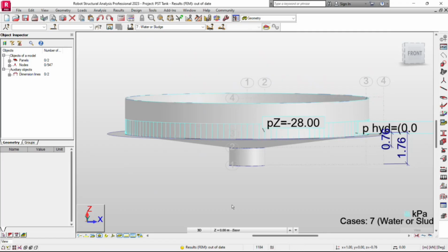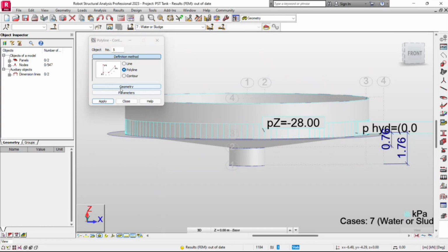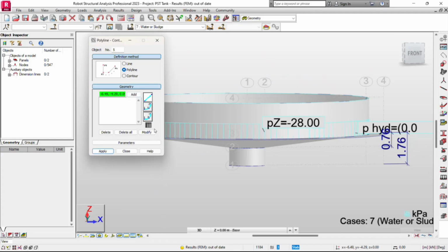All right, so when you do it, you create the polyline over here, right? That's how we created the geometry in this polyline, for example. So you're creating one by one. If you create from this point to this point and then click apply, right? Don't continue from here and then from there to the last point. You just click this one here and then go up, finish it, apply, and then create another polyline so that these elements will be separated.